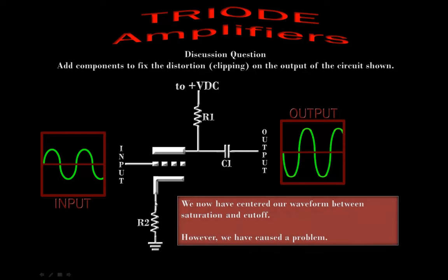So the top of the resistor is at whatever voltage this resistor is dropping. So let's say it's dropping 1 volt. Then the cathode is now at 1 volt. So when the control grid is at 0 volts, it is negative in comparison to the 1 volt of the cathode. So we've made our control grid more negative comparatively to the cathode, and that has fixed the problem.